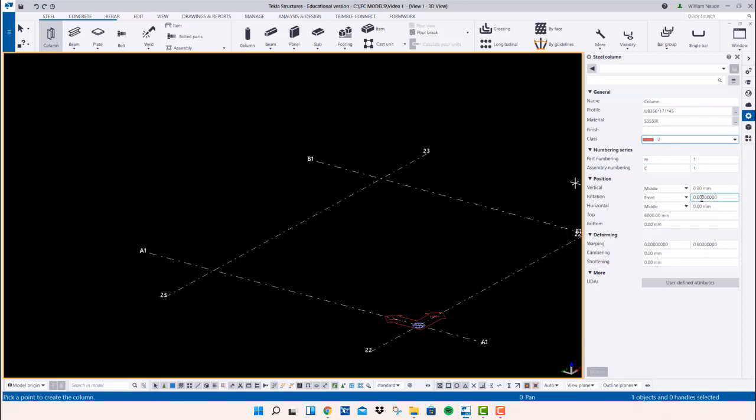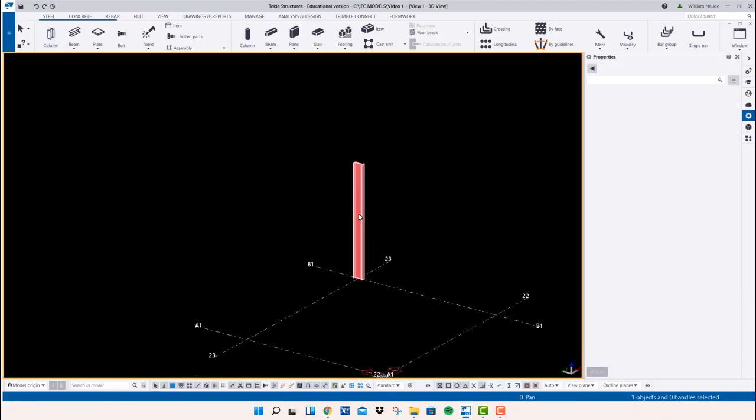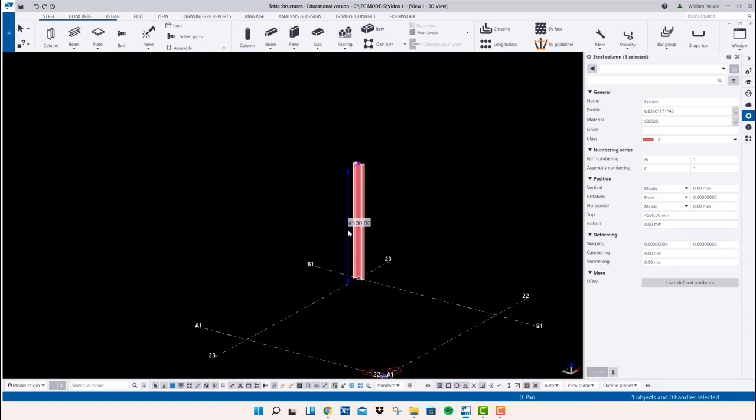And now, you already know that our total height of this entire platform should be 4.5 meters. So I'm going to change the 6,000 millimeter to 4,500 to get it automatically to the correct height. Now, I'm going to place it in, and there we go. If I click on it, it will show that it's currently on 4.5 meters.